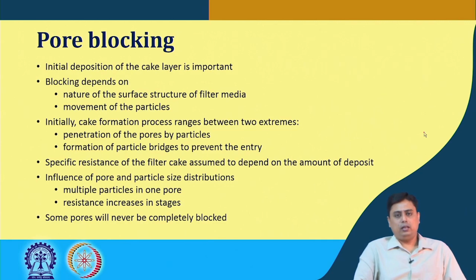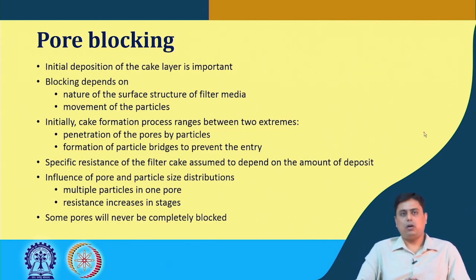Now, this blocking of pore depends on the nature of the surface structure of the filter media, its affinity towards the particle or the suspension, and the movement of the particles. These particles in suspension are moving freely, and they have the bulk velocity of the fluid. So, to block the pore, a particle has to be streamlined and targeted towards the pore, which is sometimes very difficult.